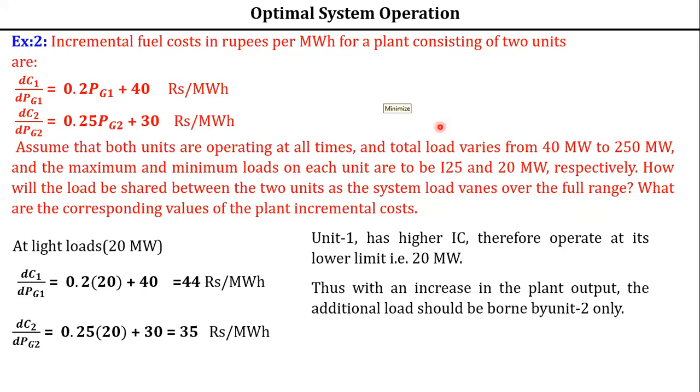Okay, that means it is lambda. So that means lambda value is 50. You are getting it, isn't it? So you see now the lambda value of both the units has become 50 at 50 megawatt. At 50 megawatt, the lambda value has become same.